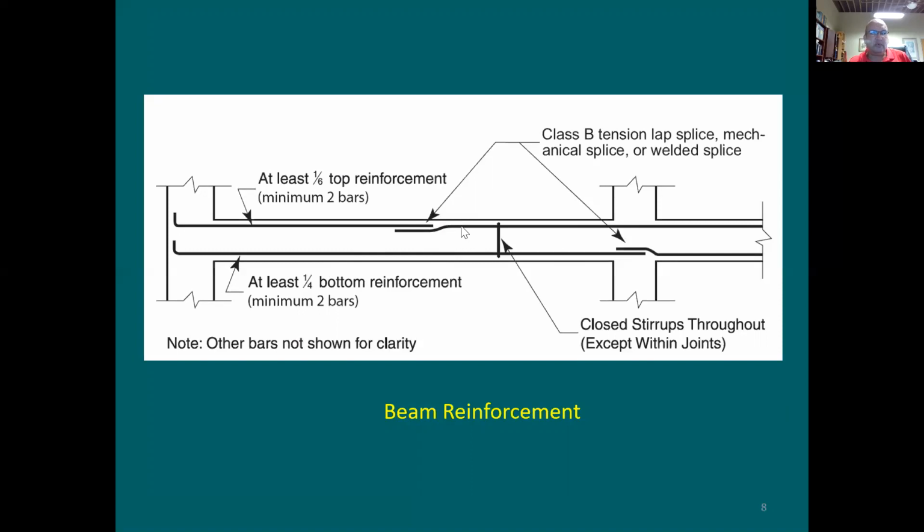And then you see what happened to the rebar? It is bent a little bit this way. In reality, it's not really bent. This is just to show you how it's gonna look like, but it's gonna be side by side. They're gonna be next to each other like this. But if you draw it this way, you're not showing that the rebars are spliced. What does it mean by spliced? It means like this. There's a lap splice between them. So I'm gonna say here, look at the splice. How did you pick the location of the splice? Is it on the tension side or compression side?